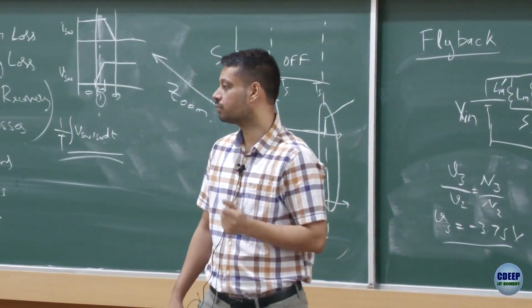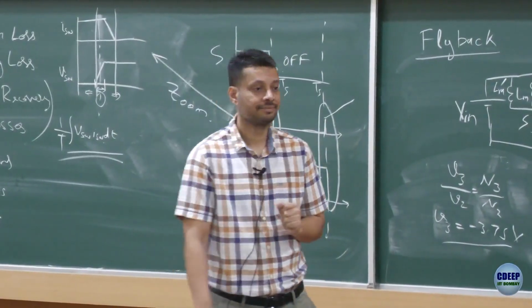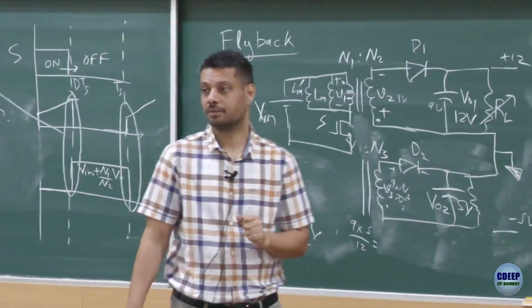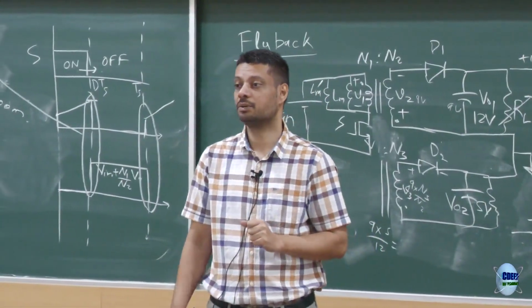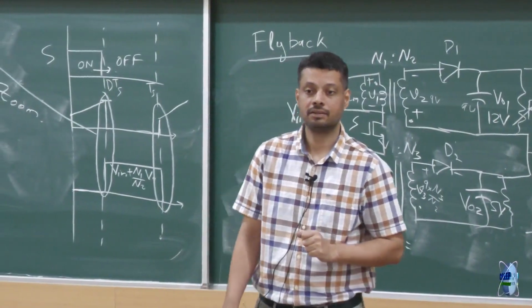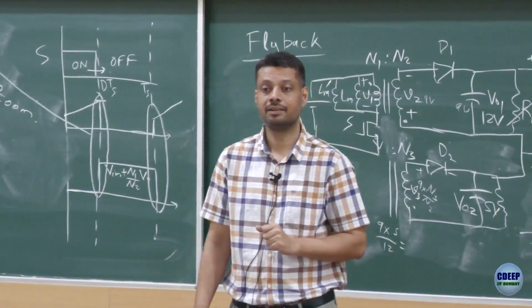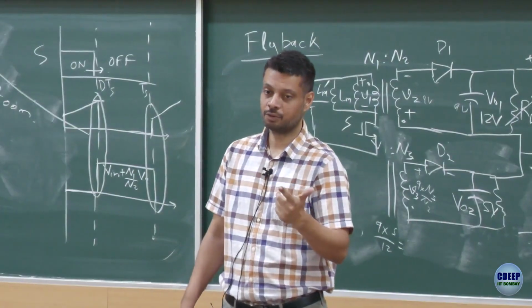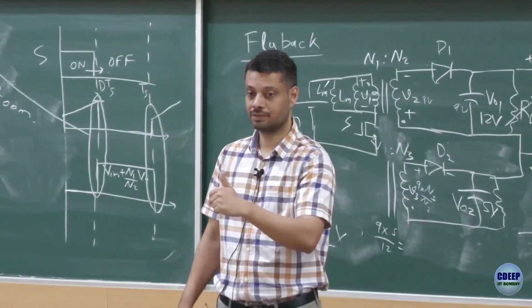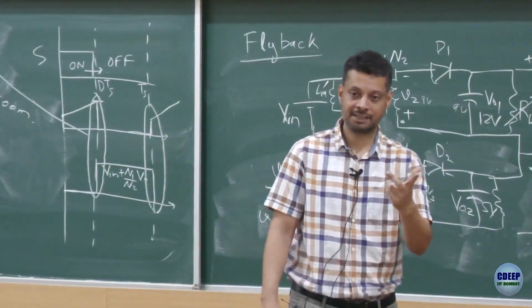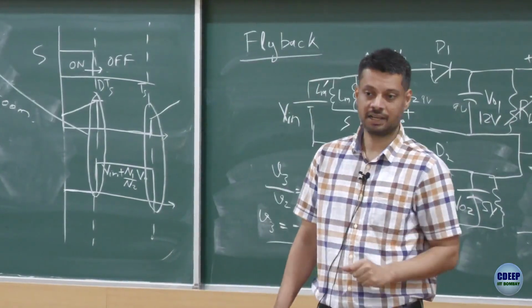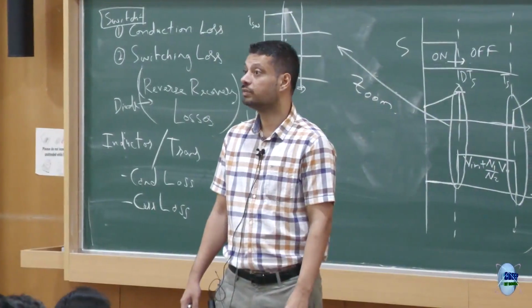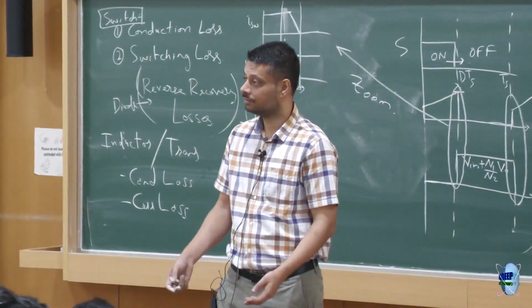Why do you want to choose boost? Buck boost can do it, right? Sorry? Oh, there is another buck boost which doesn't give negative output. I'll ask you in the quiz. But there is another buck boost circuit which doesn't give negative output. Boost will have higher D and that is more desirable.